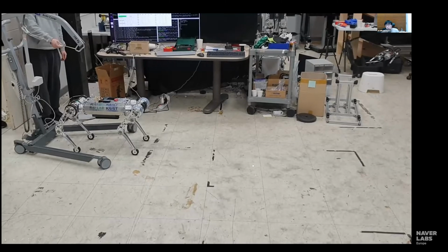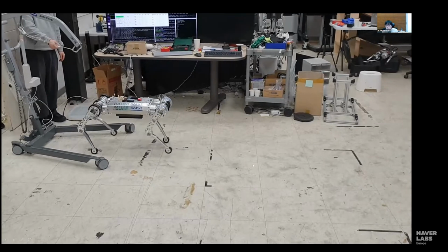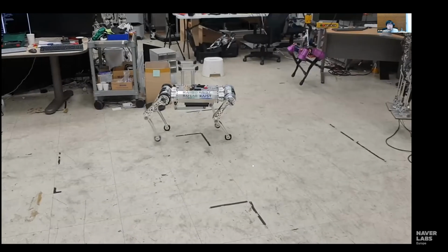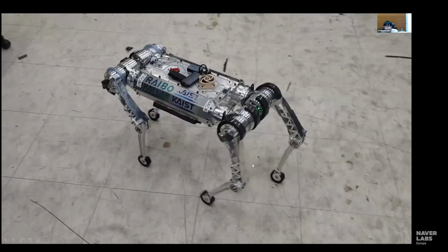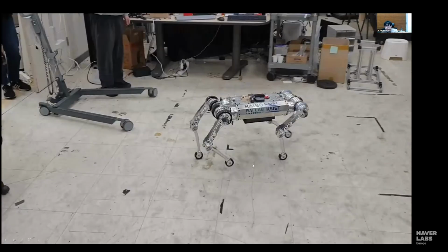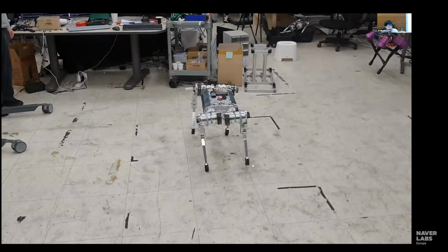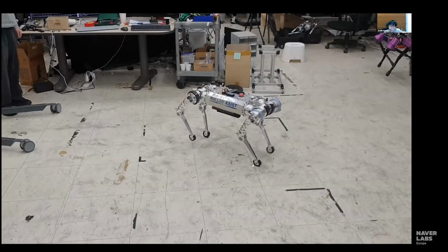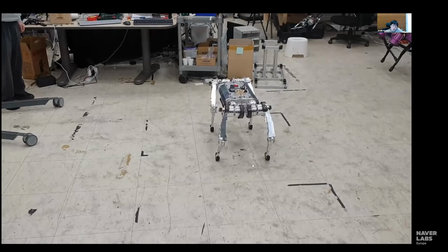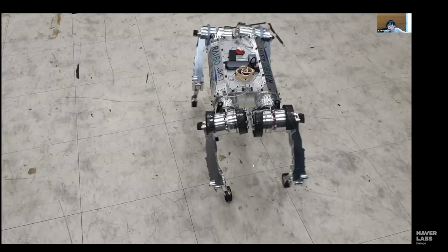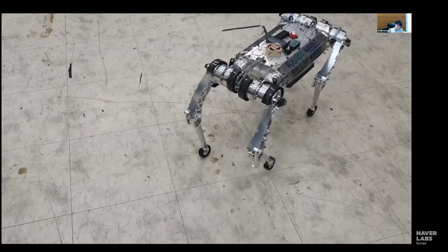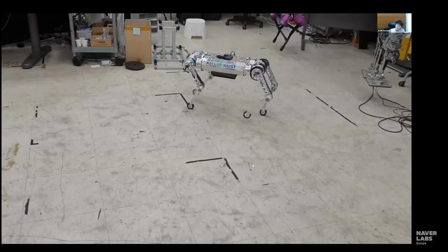So when we train the control policy for mini cheetah, we still had to model the delay. We still had to model the friction in order to transfer the control policy to the real system. But here, there is no such modeling. So this is almost like an ideal controller or ideal model.